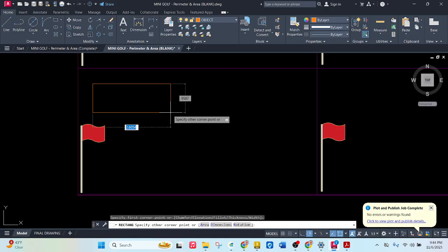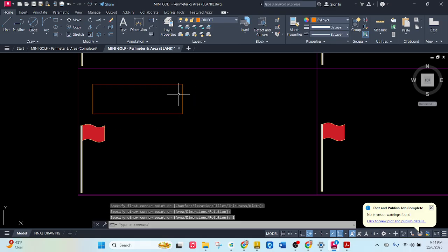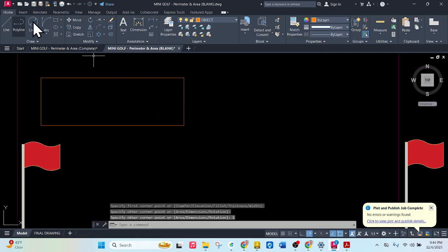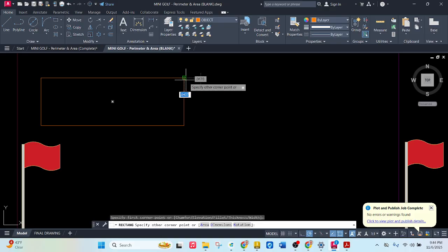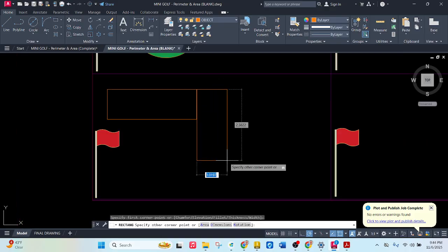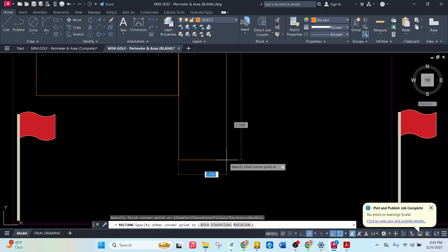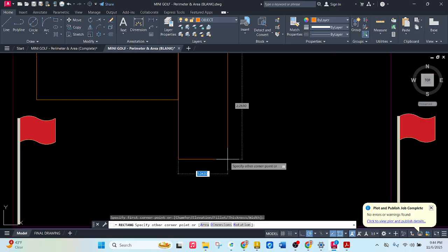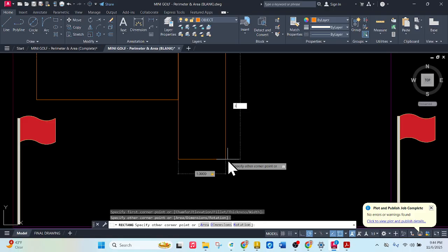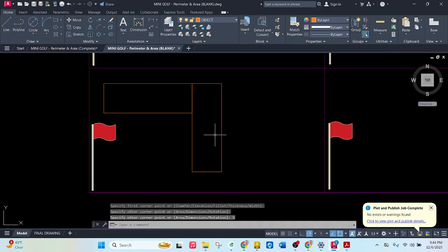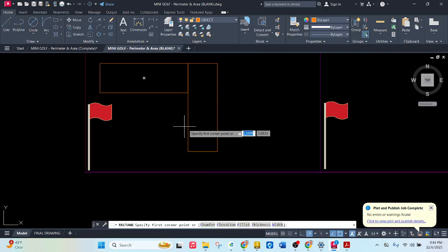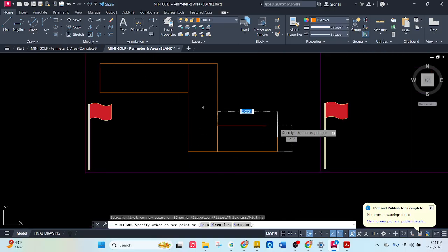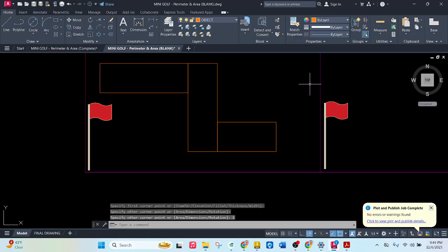It goes over 3, tab 1, enter. And then I'm going to grab another rectangle. Click this corner. Be very careful to select the corner. If you don't get it just right on it, it won't work as a hatch later. So we'll do 1, tab by 3, enter. Nice. Then we're going to go this one. It goes 2, tab 1, enter.